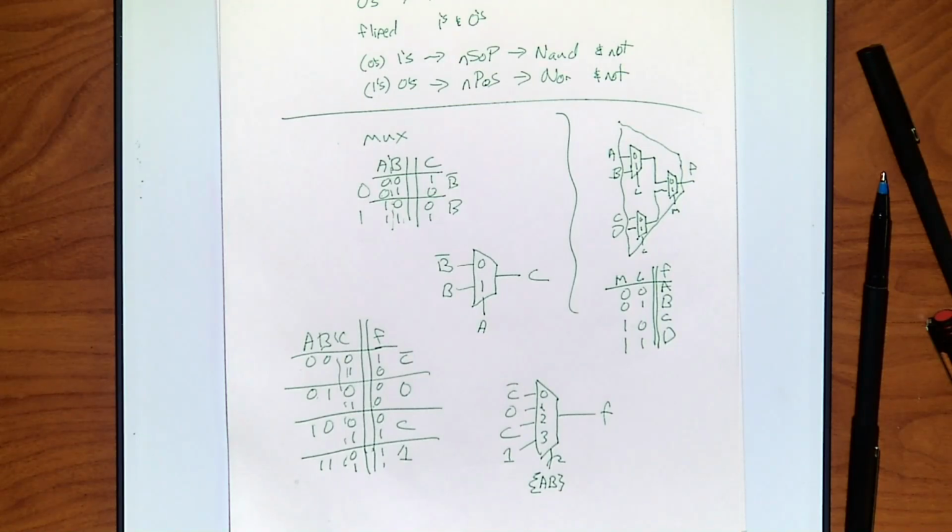So, quick question, why don't I only do this? This does not protect against any glitches. K-maps protect against glitches, this doesn't. But what protects me against glitches in this situation? Memory, I synchronize it. This is actually how FPGAs work. This is the table you're copying down. It just gets the function and copies the table down. It's got glitches all over the place. If you time it, glitches only happen at certain points, so you just don't read it when it can glitch. Well, all glitches gone.